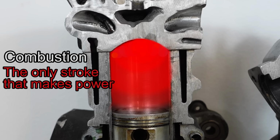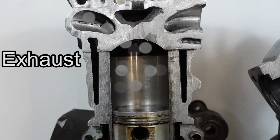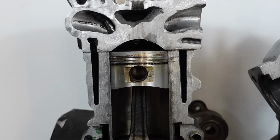By the time the piston reaches bottom dead center again, all the air-fuel mixture has been burned, and we now have exhaust gas, or the remains of combustion, inside the cylinder. As the piston moves up once again, the exhaust gases leave the cylinder and exit through the exhaust piping, catalytic converters, and mufflers out into the atmosphere.